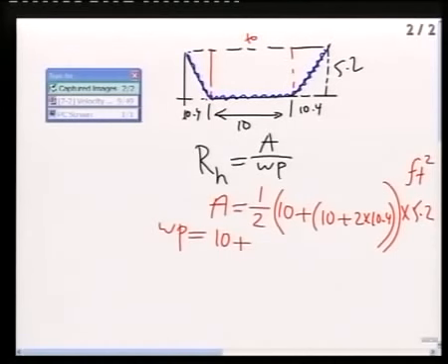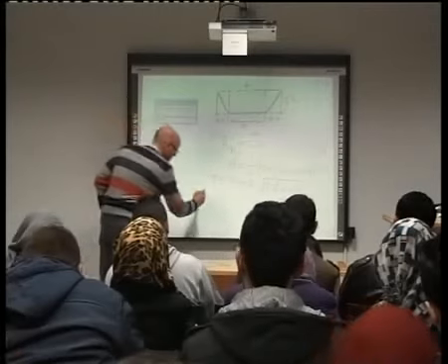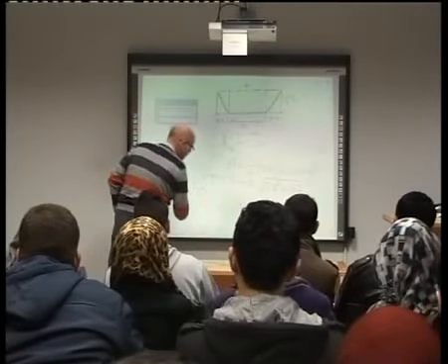So it's 2 multiplied by the slanted side, exactly. Like that. Just you go back, you find hydraulic radius, you put it in that equation, and then you can get the value of the boundary shear stress.